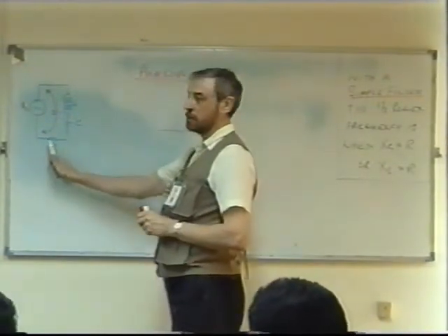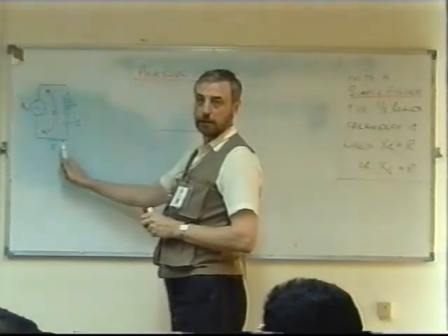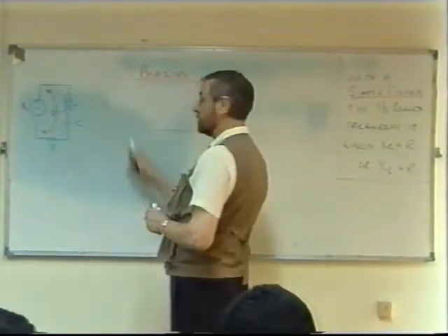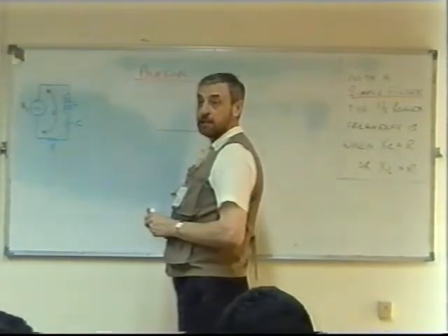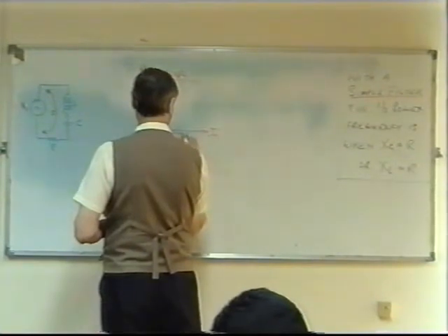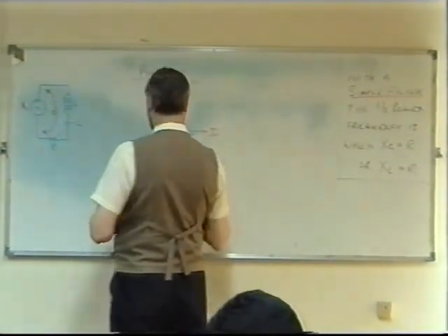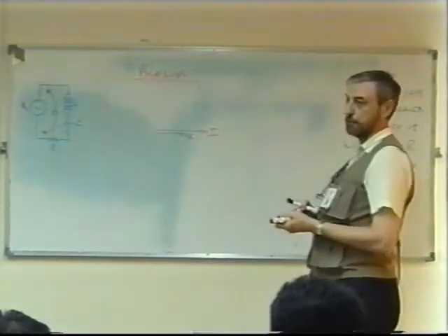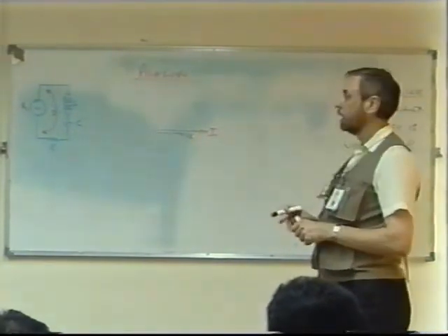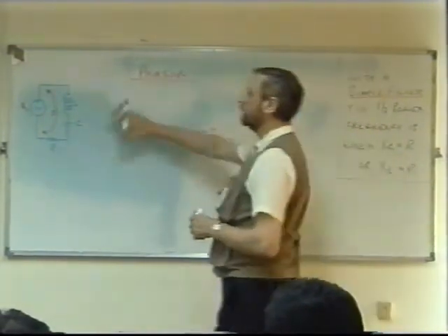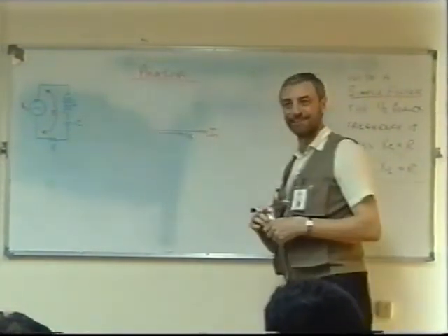First of all, the voltage across the resistor. What's the phase relationship? The same. Yes, in phase with the current. That's VR. What about the voltage across the inductor? The inductor will be 90 degrees out of phase. Is it going to lead or lag on the current?